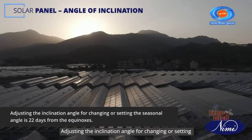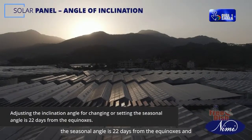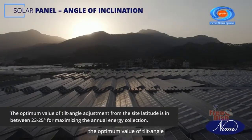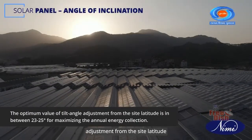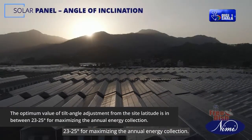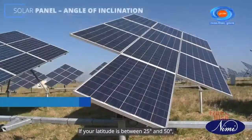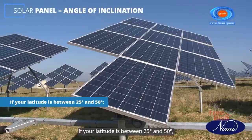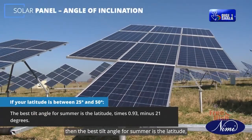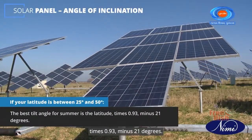Adjusting the inclination angle for changing or setting the seasonal angle is done 22 days from the equinoxes, and the optimum value of tilt angle adjustment from the site latitude is between 23 to 25 degrees for maximizing the annual energy collection. If your latitude is between 25 degrees and 50 degrees, then the best tilt angle for summer is the latitude times 0.93 minus 21 degrees.